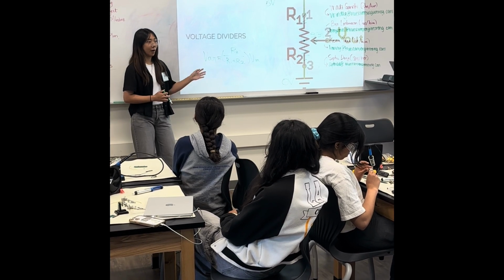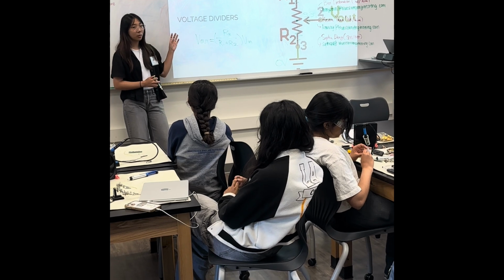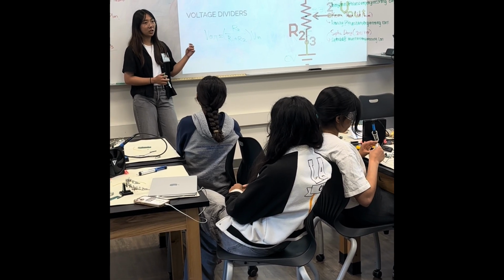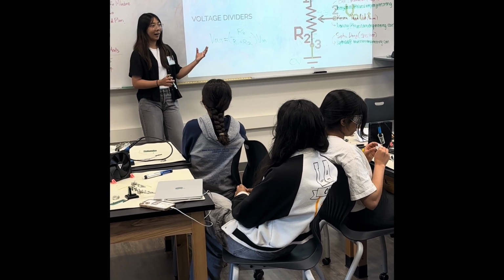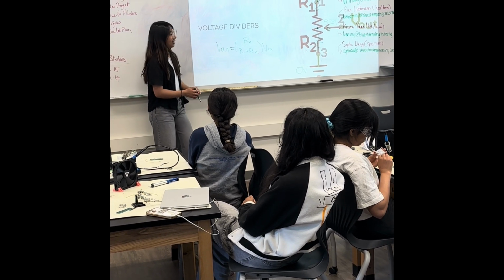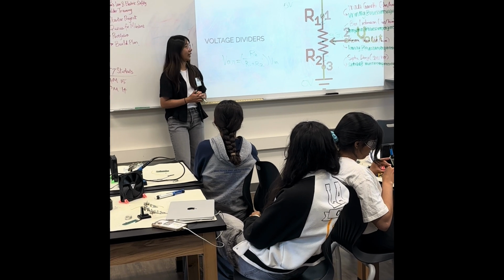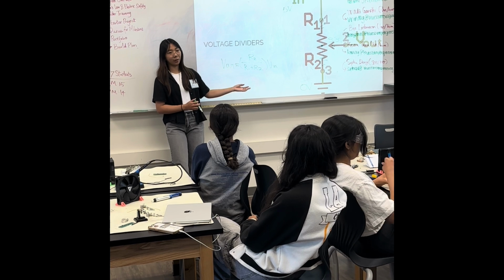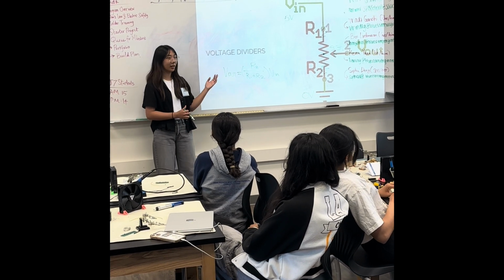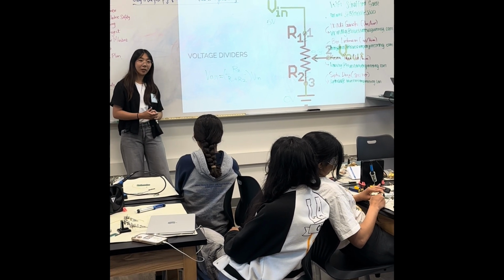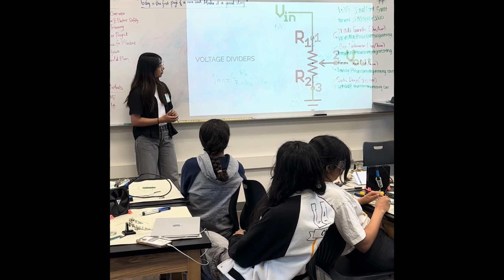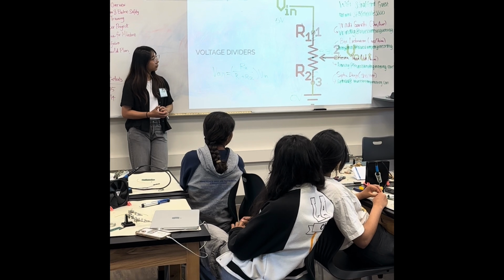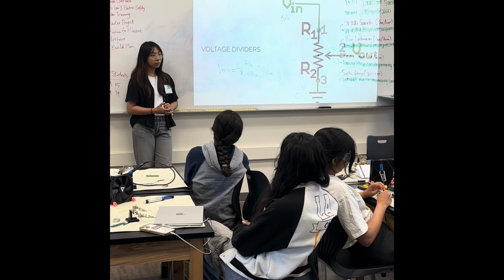We're going to go back to that problem that I talked about when we first introduced Ohm's law, where the resistance is really tiny compared to the voltage, and then your current will be way too high and things will not work. So typically we pick something like 10K and 20K for a voltage divider from 5 volts to 3.3 volts, and it usually works pretty well. That's the most common one, so you guys will probably be building that circuit. This is really important if you're using a Raspberry Pi. Anybody using a Raspberry Pi in their projects, you should know how to use these. Anybody using Bluetooth in their projects,